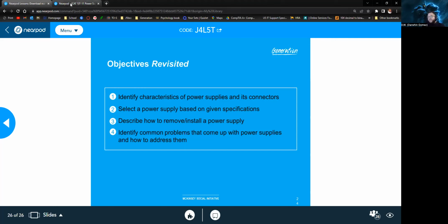If you're being practical in real life, what would you aim for? 1,500. Good. So yeah, 30% is the minimum, so it will be 1,300. Okay. What if what you needed for watts was 500? How much should your power supply unit provide? What's the minimum you should look for? 650. Good job, Madison.